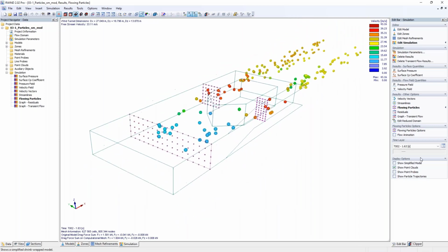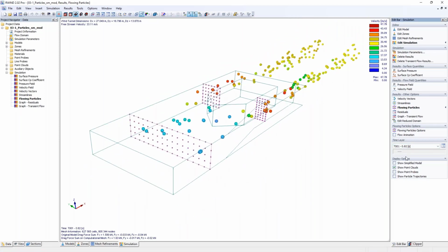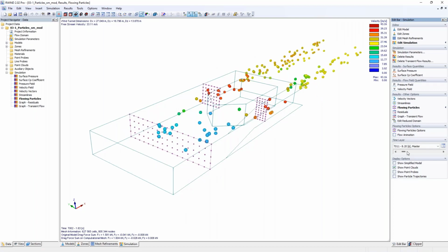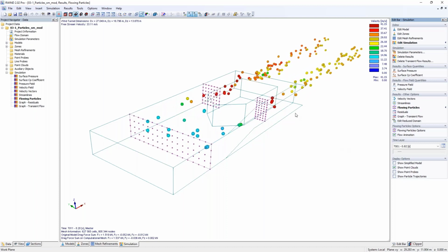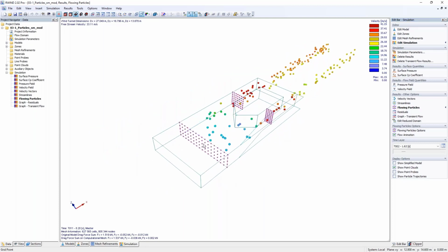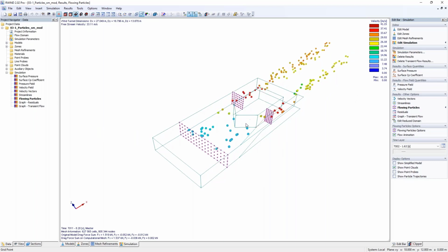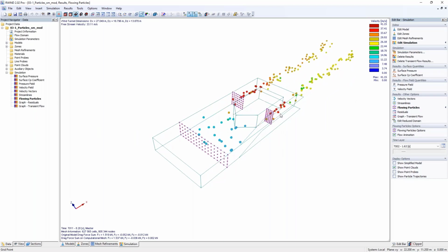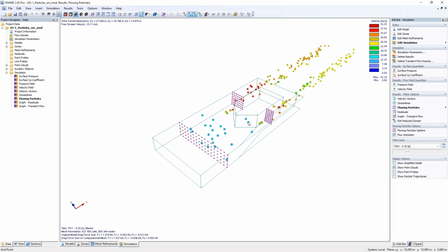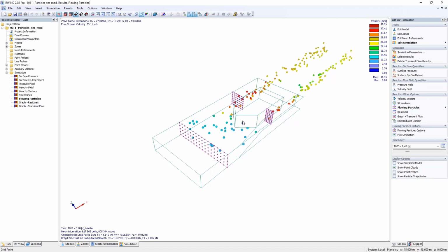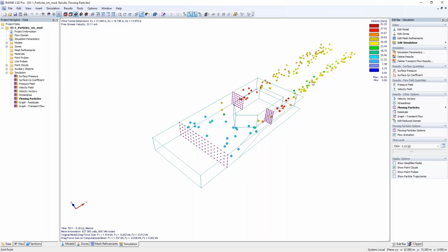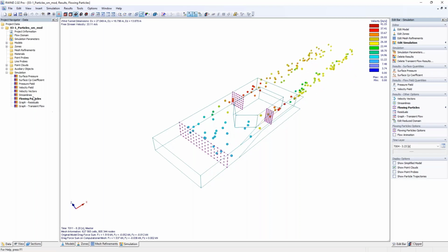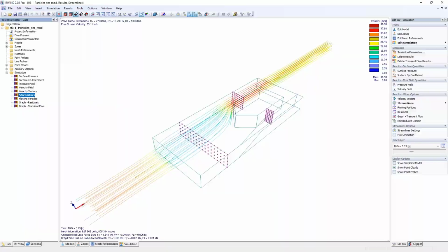And you can then animate them. So you can choose your own time layer if you want to with this bar. So the master time layer is, for this example, at 8 seconds 20. And you can also do a flow animation, which would then, of course, show you how these particles will behave. So you can see that they are more or less being created in here and then choosing their way to the left or the top, the right, of course. And you can also see the velocity. So they are more or less being put on the surface, slow down a bit, but then being accelerated once again and flow through our animation. All right, so let's switch back to streamlines so that it will not slow down my computer.